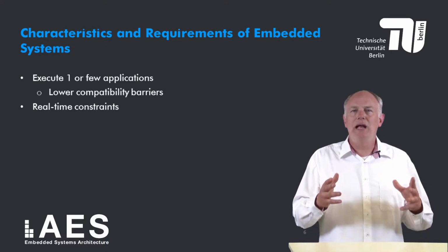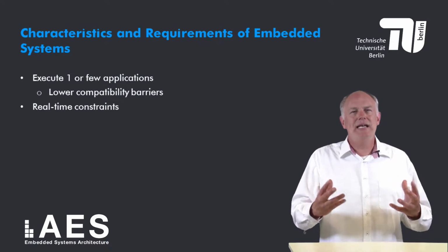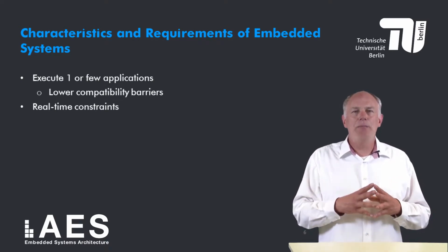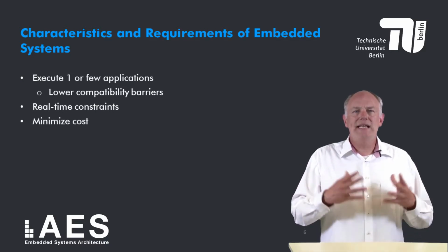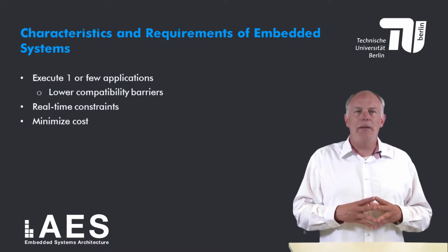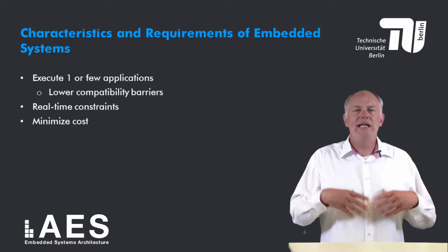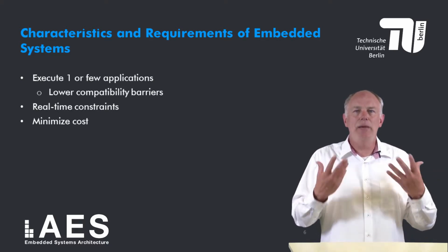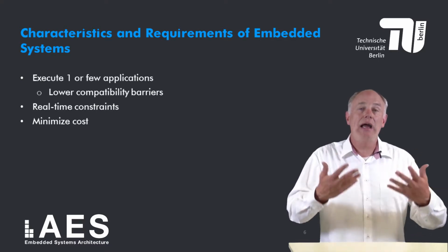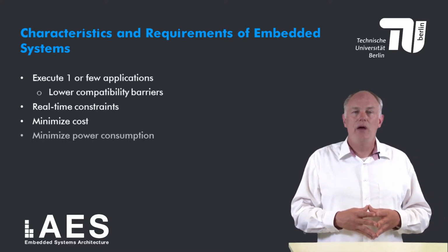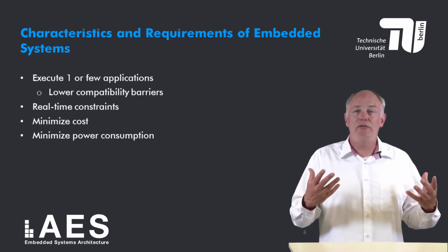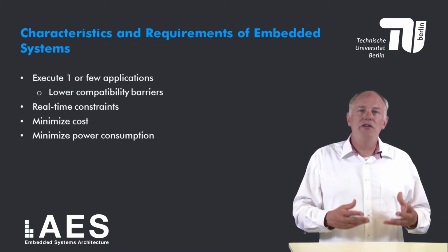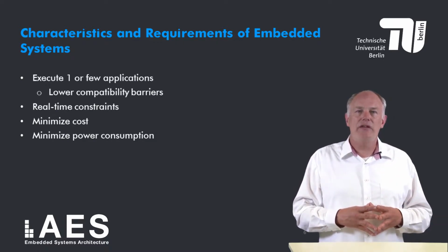That means that they must complete their task on time, otherwise it is considered a failure. I will say a bit more about real-time constraints on the next slide. Third, price is often the key factor in the design of embedded computers. Of course, there are performance requirements, but the primary goal is often to meet the performance needed at a minimum price, rather than achieving higher performance at a higher price. Fourth, because many embedded systems are powered by batteries and do not have a fan for cooling, low power consumption is another strong requirement of embedded systems.